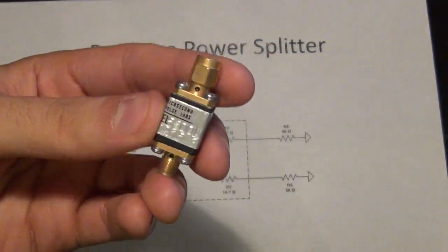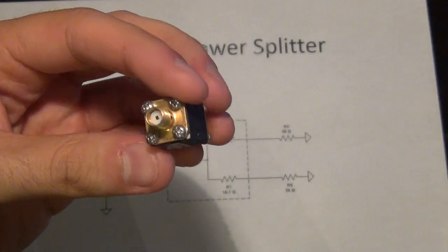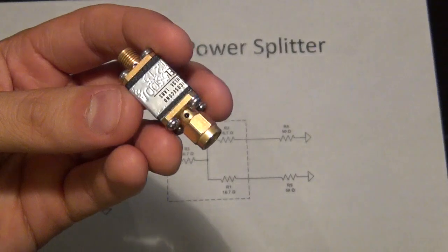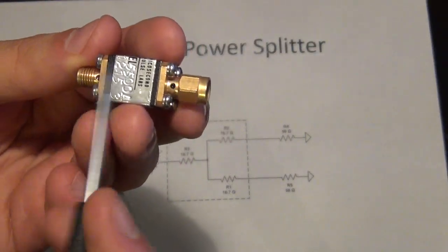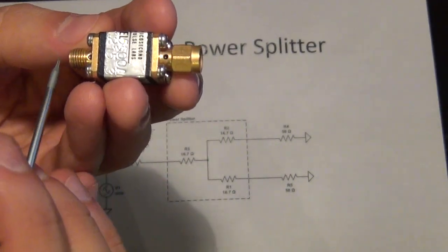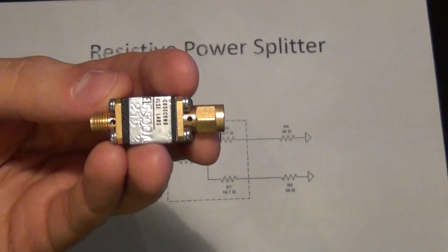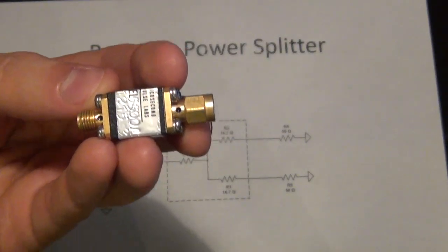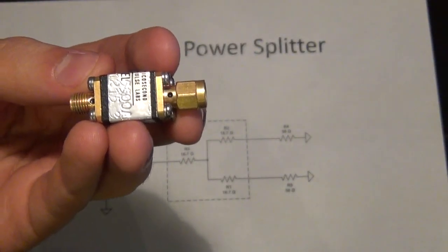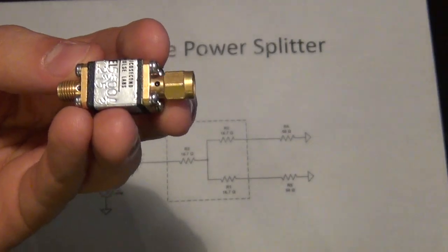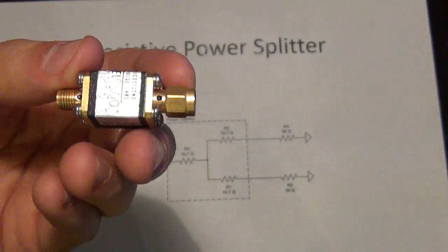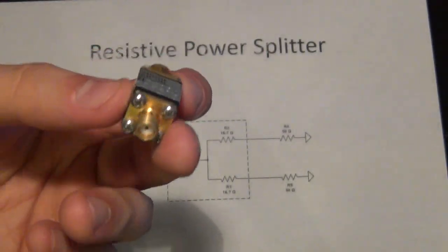Another really common component is a DC coupling cap. So this is an SMA, again we can tell because of this white Teflon dielectric. This is an AC decoupling cap, meaning that it's just a series capacitor. And this is used to isolate DC from the instrument. So if I were to put in my signal here and my signal has some DC content, let's say it's an amplifier and it has a 3-volt output voltage, on the other side, I cannot connect this to some of the instruments because a lot of instruments actually cannot take DC directly. So by using a DC coupling cap in series, I'm able to totally separate the DC from the AC side. So this is very common.